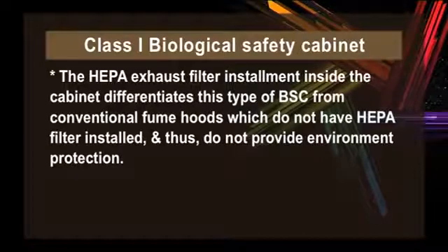The HEPA exhaust filter installed inside the cabinet differentiates this type of biological safety cabinet from conventional fume hoods, which do not have a HEPA filter installed and thus do not provide environment protection.